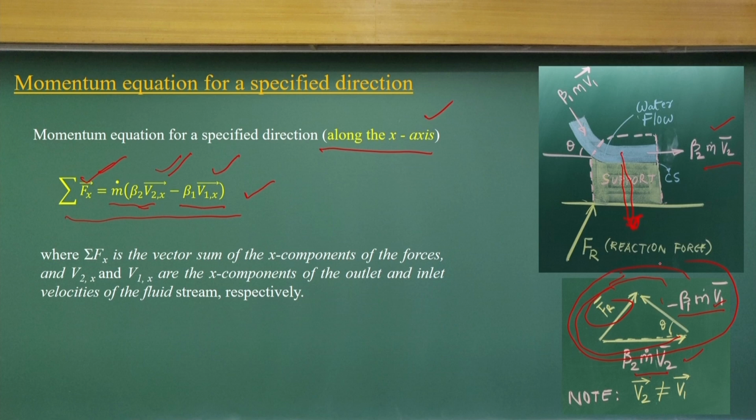That is what we can simplify; you can solve this directly. These momentum fluxes are equivalent to forces: what is coming into this control volume and going out from it. These two forces balance with a resultant force, which vectorially you can find, that is the FR value, the reaction force. So, this way we can simplify, either by considering this control volume or by writing the force vectors due to the momentum flux in and out. From there we can get the resultant force components and the reaction force component.